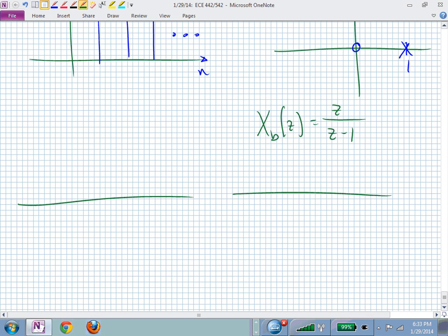Or we could say, well, I want to play in the continuous time. I'm going to stay with Laplace. Somebody goes, well, I need you to design a controller in a computer. You go, now I have to go into the Z-plane, maybe, to design that controller. You need to work in the discrete time so that you can give somebody a difference equation and they can go code it up into their machine. And now it'll sit there and crank numbers and do the filtering or the controlling that you need it to do. All right. Did that help answer your question about S and Z?